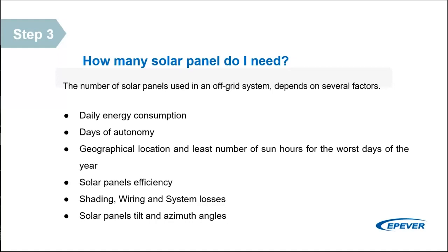Of course, these are all based on the testing conditions, which are 1000 watts per square meter of solar irradiance, an air mass of 1.5, and a temperature of 25 degrees. Each of these elements will have an effect on these values. So when you see ISC and VOC, please note that this is based on the testing conditions in the lab.